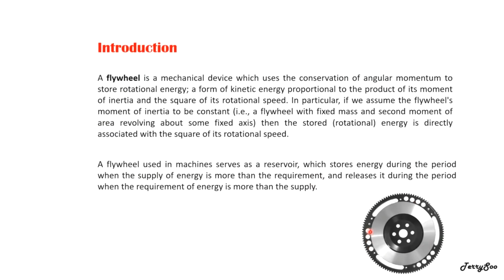This excess energy will cause the flywheel to rotate at a higher speed. The rest of the three strokes, that is the suction stroke, the discharge, and the compression stroke, all require energy. So the excess energy stored during the power stroke will be given out to run the rest of the three processes, that means the three strokes.